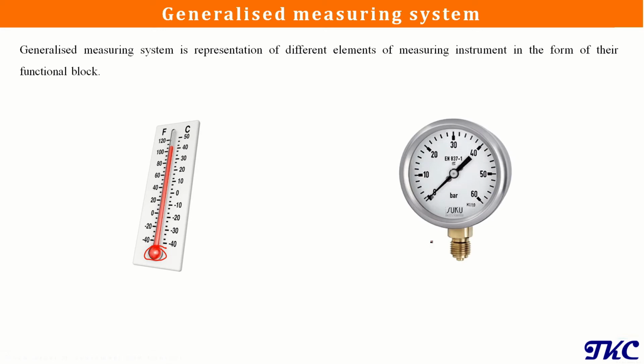Next, suppose we have a pressure gauge. Again, in a pressure gauge we will have an element which is going to sense the pressure. Normally, one of the elements that we have with a pressure gauge is a diaphragm. The diaphragm is like a disc, and when we apply pressure from one side, it gets deflected, and that deflection, that displacement, we can measure, and it will be an indication of the pressure. So here this diaphragm becomes the sensing element.